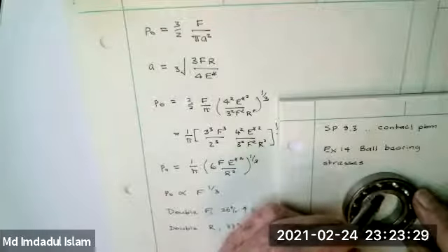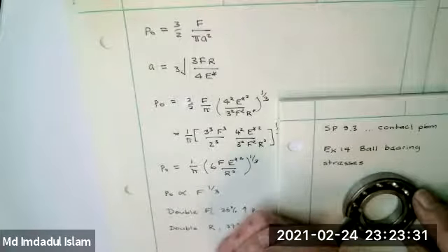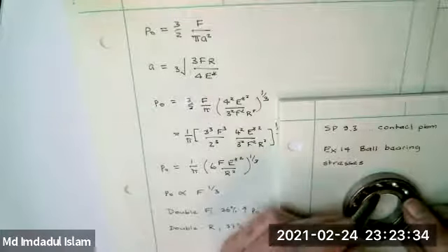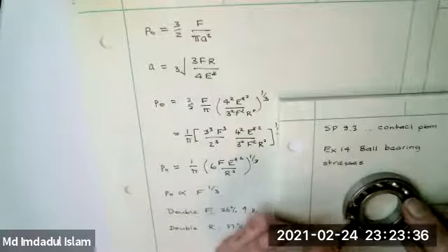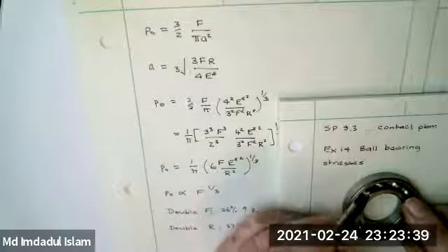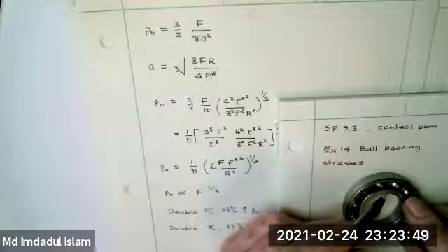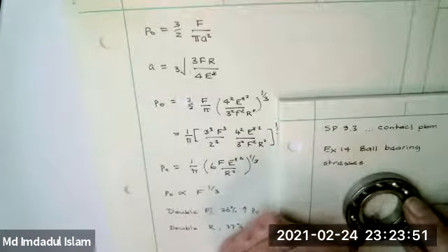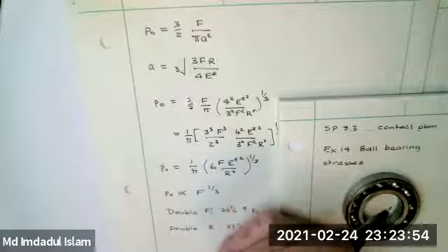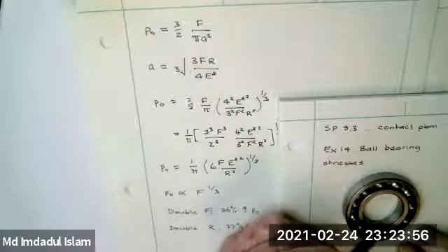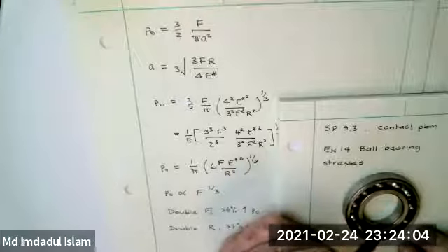And this is one of the reasons why these stresses are important, because this thing here has seen several of these balls as it went around, and so it's seen their stress go off and on, and so has the outer radius. Okay, and for that matter, the balls themselves are spinning, and so they see contact stresses on either side, and they switch off and on. So this is a real candidate for fatigue. And so one of the reasons you want to analyze the stresses of something like this is you want to make sure the shear stress is not close to yield, and that'll help you avoid fatigue.